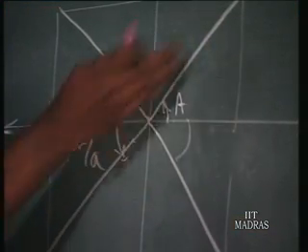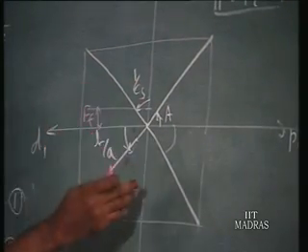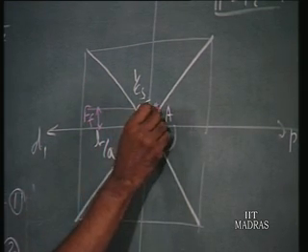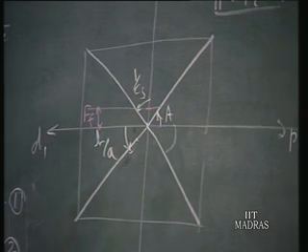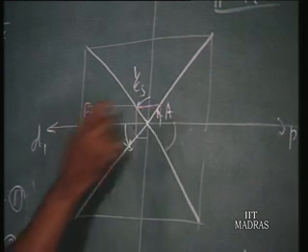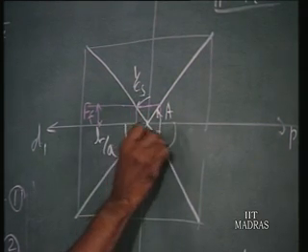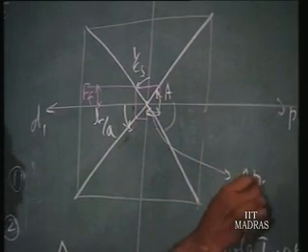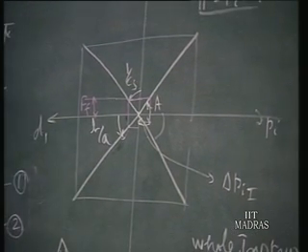Using the characteristic curve, a line through the origin, since all these characteristics are linear, use this to bring it across. From this friction force, what is the corresponding error in the input signal? You project it to the input axis and also to the output axis using this characteristic. So for FF, the amount of error here I will call delta PI1. This is the error from the first error source, FF.